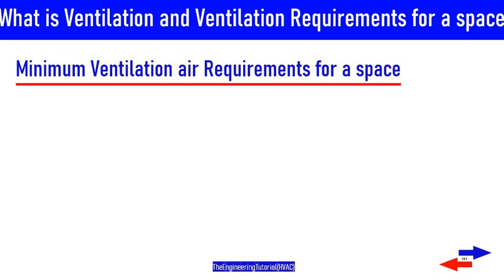When the outdoor air is not moving due to wind, the amount of infiltration can drop to zero. Instead, it's common to introduce the outdoor air through the HVAC system, not only to meet the ventilation needs, but also to maintain a positive pressure relative to the outdoors within the building.